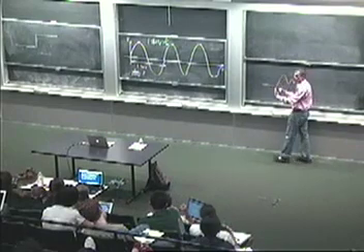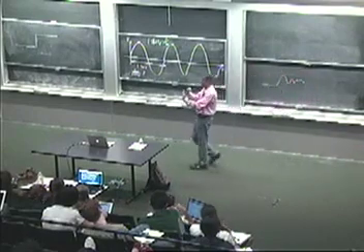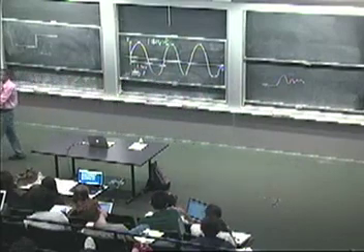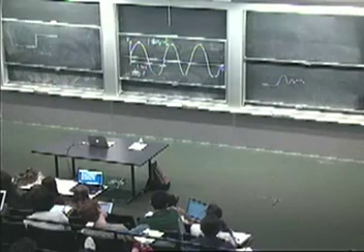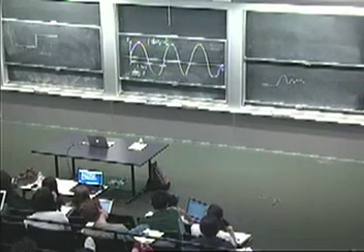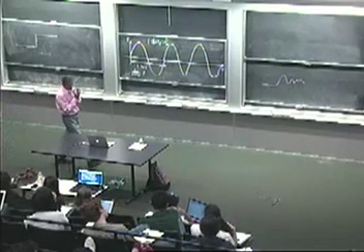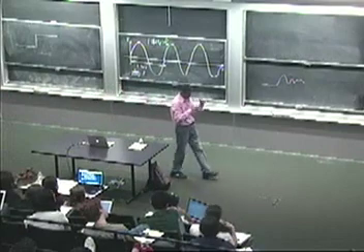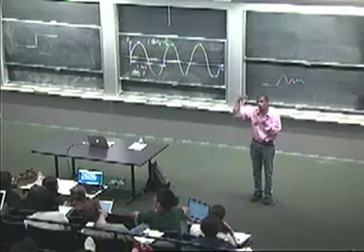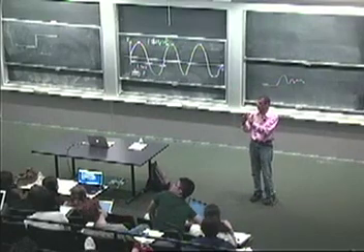What I'm going to end up with is this combination of zeros and ones that are sort of random, confusing the receiver, because we're not giving enough time for the 0 to settle down, and similarly, when we go from a 0 to a 1, we're not giving enough time for the 1 to settle down. That's what this eye diagram was referring to, where we found this confused case, and then when you have noise, some of the zeros get moved to a 1 anyway, and ones get moved to a 0, and we end up with this very crowded picture.